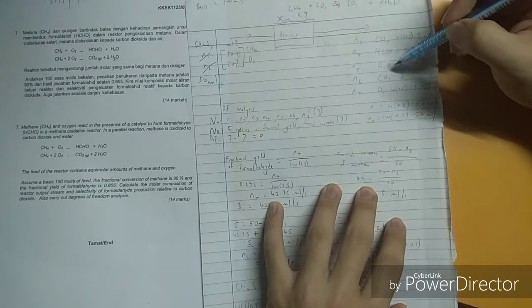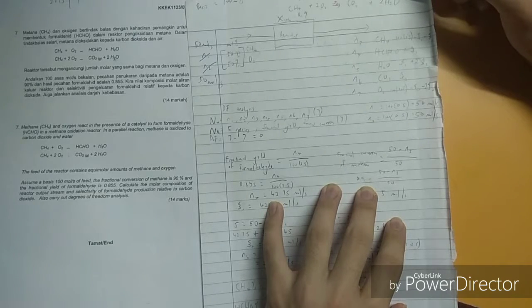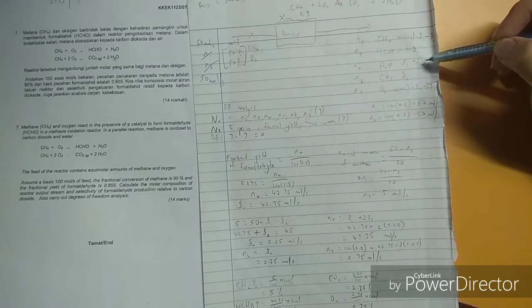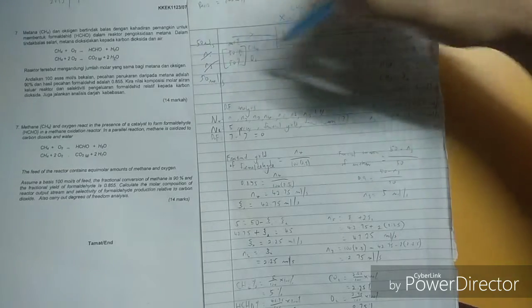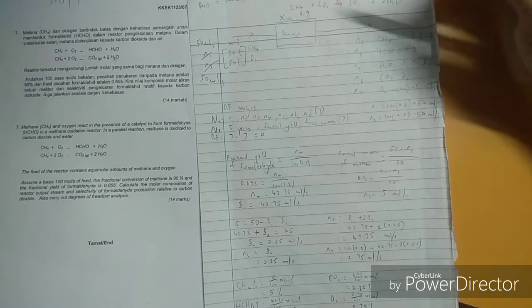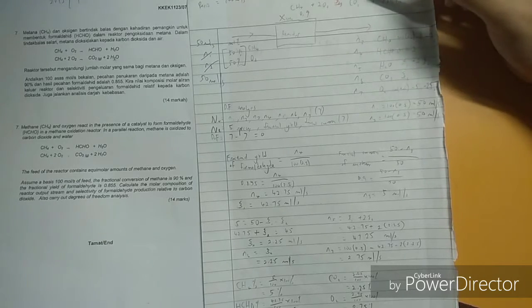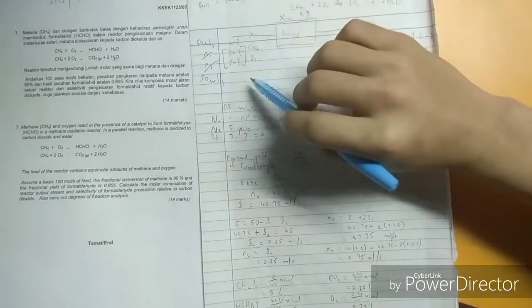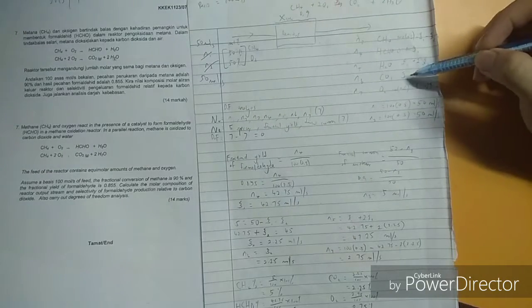Then after that is the water. Water is H2O, so water reacts in the first equation and the second equation. So we just put it as C1 plus 2 C2, because the initial is 0, so we just put 0 plus the C. And N6 is the CO2. CO2 reacts in reaction 2 only, so the initial is also 0, so we just put C2 because the